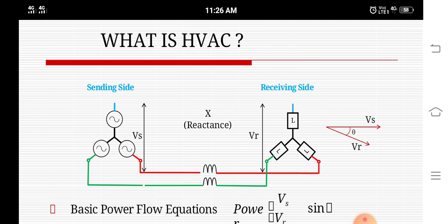So many things are connected with SIL. SIL means surge impedance loading. The maintenance of constant voltage at the two ends requires reactive power control from inductive to capacitive. As the line loading is increased, the reactive power requirement increases, and also with increase in the line length.